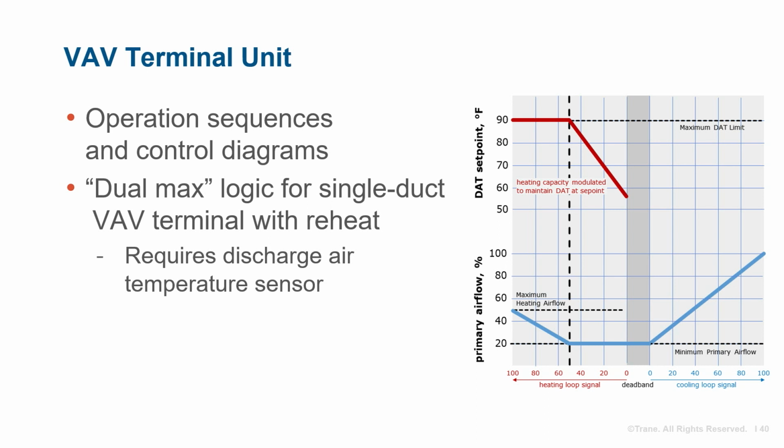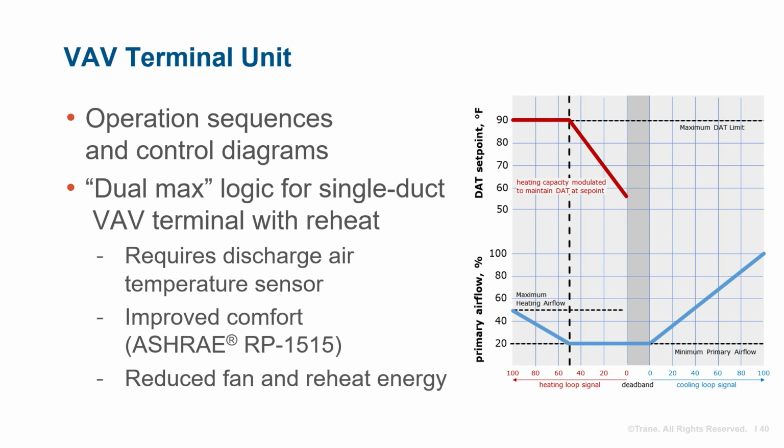At this point, the VAV will start to provide more air while maintaining discharge air temperature. Particularly in cold climates, this prevents extremely high heating discharge air temperatures in spaces that have large heating loads. The lower discharge air temperature reduces stratification, improves comfort, and uses less energy.